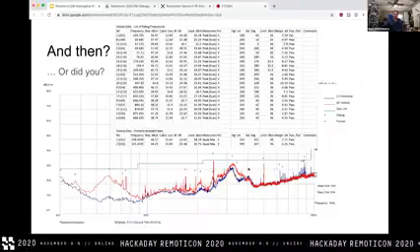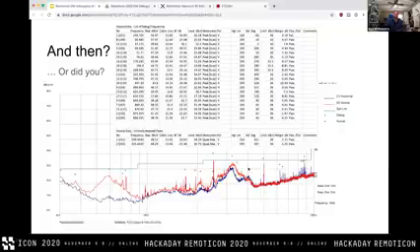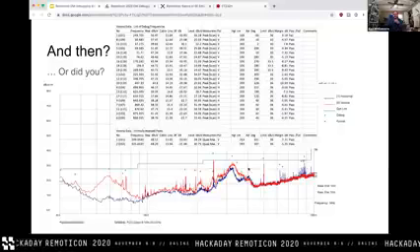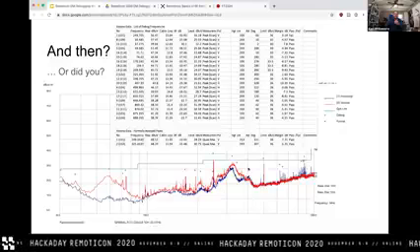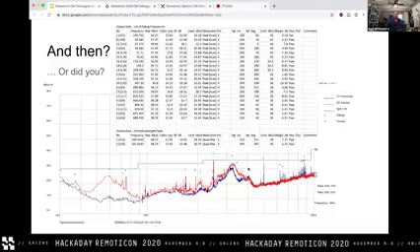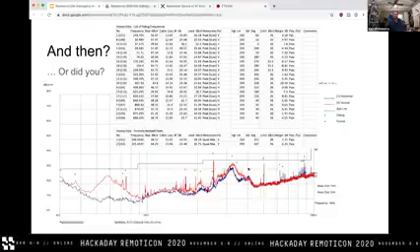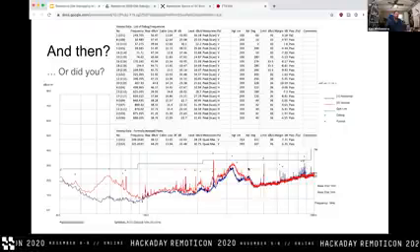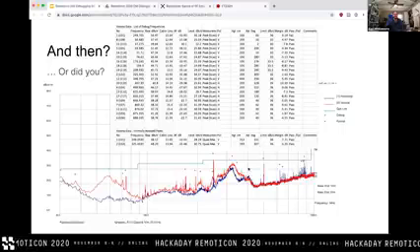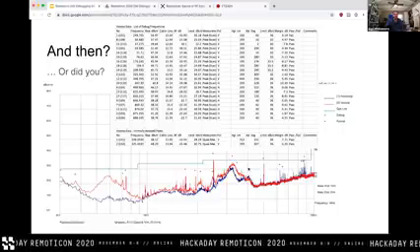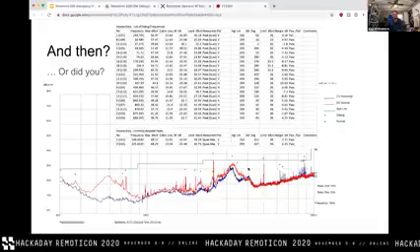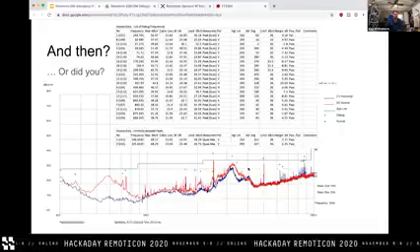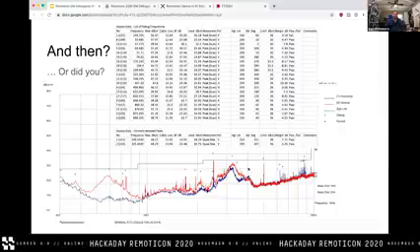And this brings up actually a critical aspect of testing, which is that your device operates in different modes at different times. And in order to have an accurate test, you do need to run the device under all conditions for the test that it might possibly encounter in the real world. So in particular for this device, it's a PoE powered device that can also be powered by DC. So there's one power condition that may or may not be true.